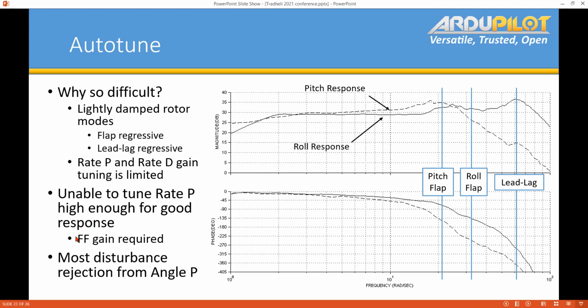So helicopters rely on feed forward, right? Rely on that feed forward gain. And essentially that's just like stick to swash plate. That's all it is. There's nothing being fed back. You're just putting a straight gain into the swash plate to then command a rate. And so that's what that guy's doing. And so in the perfect world, right, we could fly a helicopter strictly on feed forward gain if we had no disturbances, and it responded exactly accordingly to that, right?